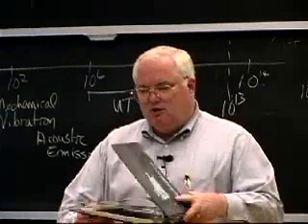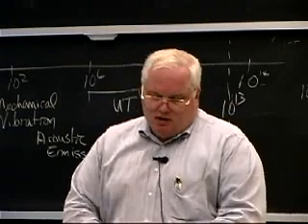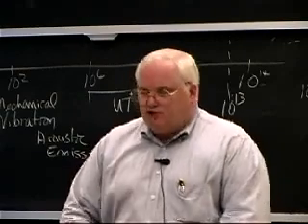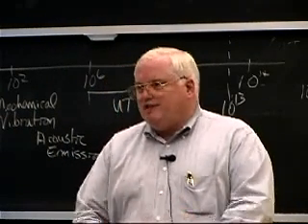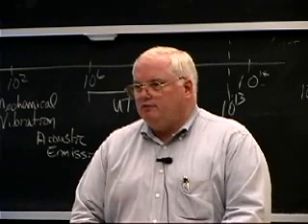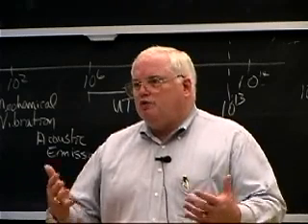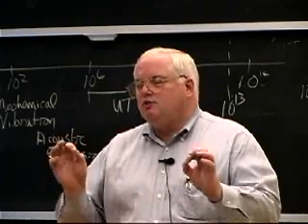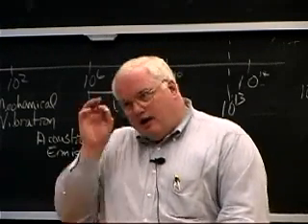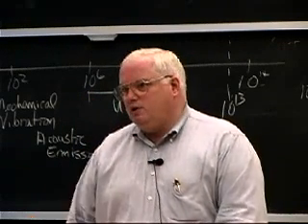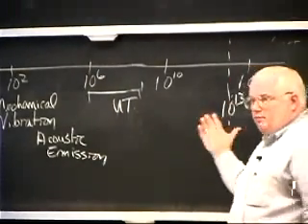Now the problem is this little handy-dandy book probably costs $700. And there's about a dozen of them out there. So you can literally spend $5,000 or $10,000 just by owning a set of the standards. So this is a standard you can call out. It's sort of subjective. There is no standard for absolutely pure aluminum castings that have no flaws. Aluminum castings will always have some small porosity. In fact, the tightest spec you'll have in here has some very fine porosity, but it's only 10 or 20 thousandths of an inch. And that's not usually big enough in a metal. It would be in a ceramic, but in a metal it's not big enough.